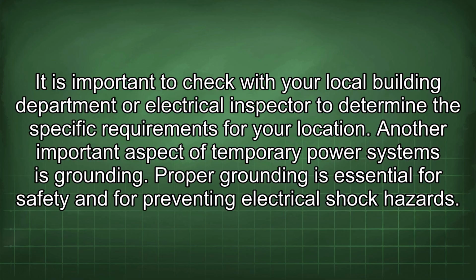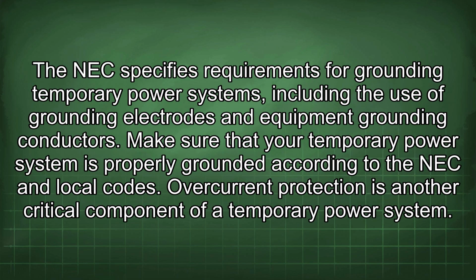Proper grounding is essential for safety and for preventing electrical shock hazards. The NEC specifies requirements for grounding temporary power systems, including the use of grounding electrodes and equipment grounding conductors. Make sure that your temporary power system is properly grounded according to the NEC and local codes.